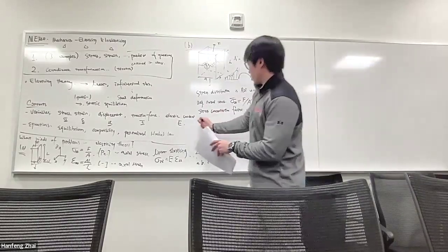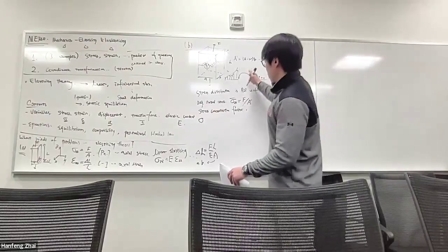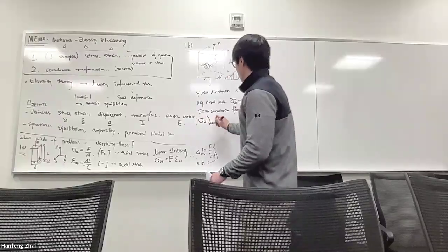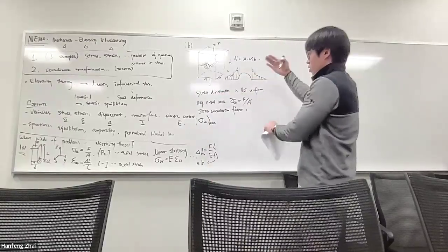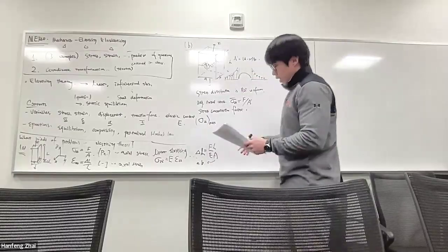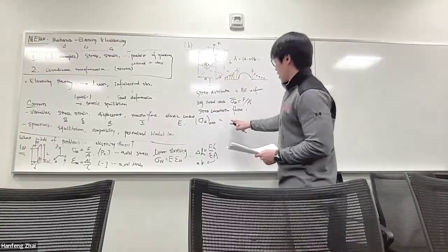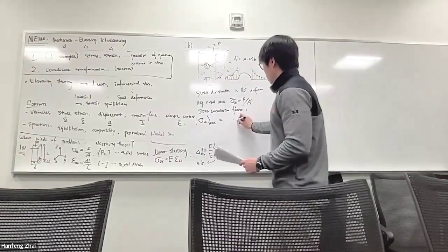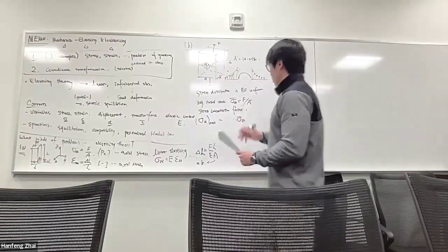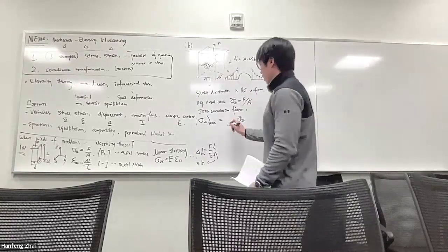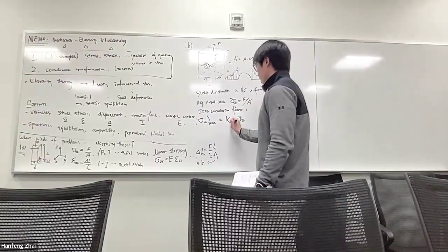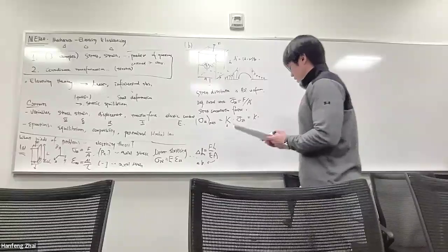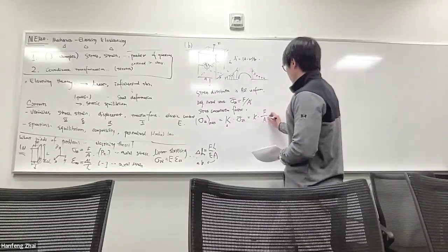How do we use this? We first calculate the maximum stress, or if we know the maximum stress over the whole distribution around this hole, we call it sigma ZZ max, it's going to be some constant, some variable times the average stress, which we just defined right here. So what is this factor? We then call it a stress concentration factor. You can call it K. You can use whatever letter you prefer. So if you plug it in, it's written in the form of K times force divided by the new area,